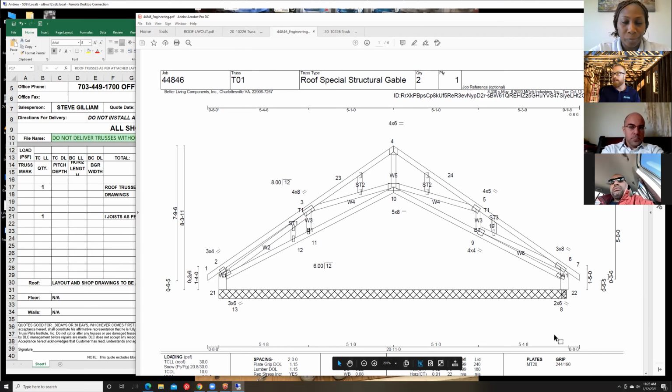Awesome. So when you have a gable end truss, you need to put headers above your window because there's load coming down. When you have some sort of scissor truss or some sort of free spanning truss instead, then there's no load coming down that wall. You do not need headers on that rear unless it's needed for rigidity purposes for wind bracing or something like that.